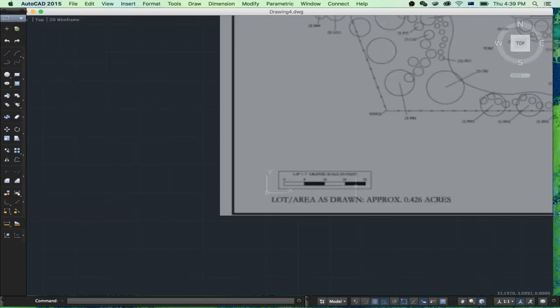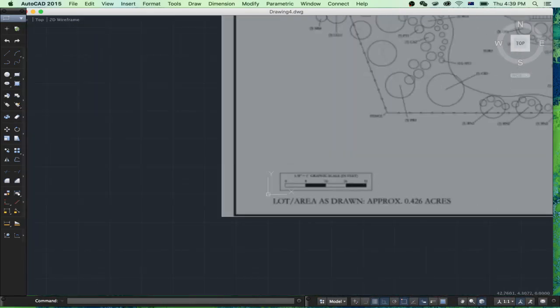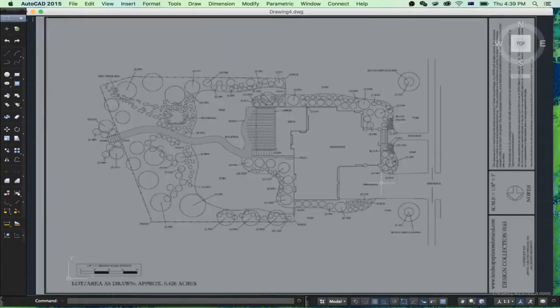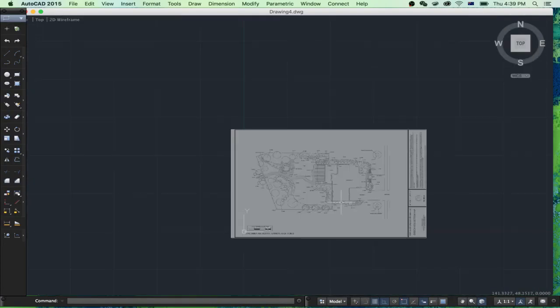Okay, I'm trying to zoom out, but the computer won't let me. I can't zoom out anymore. This is a time when I can use zoom, Z, Enter, E, Enter. For some of you, remember we tried that? We go Z for zoom, Enter, E for extents, Enter.